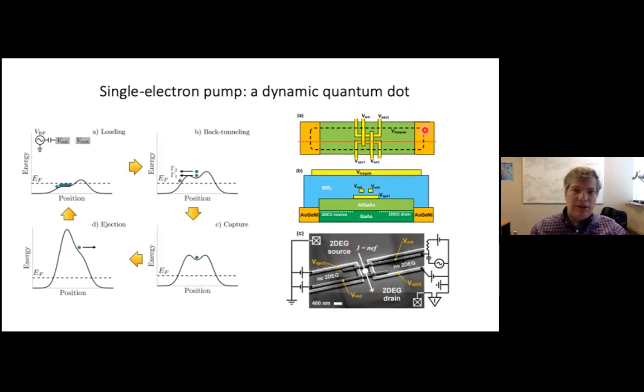So if you look at this diagram on the top, this is a top view of the device, sort of looking through the top gate down to the gates on the surface. So you can see these local gate electrodes in gold. The U-shaped ones together form a 1D constriction, a 1D channel.